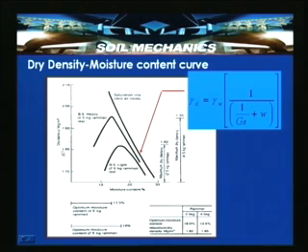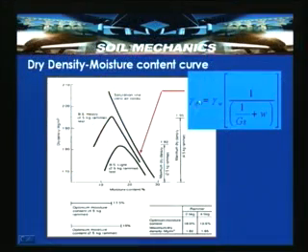optimum moisture content with 1.81, where you will see the increase in dry density indicates that more air could be expelled quickly, so that the additional dry density has come. This is actually the effect of compaction energy on the soil, which we will be discussing in detail in the forthcoming slides. This line shows the saturation line, which has been obtained from the expression gamma D is equal to gamma W into 1 by Gs plus W.